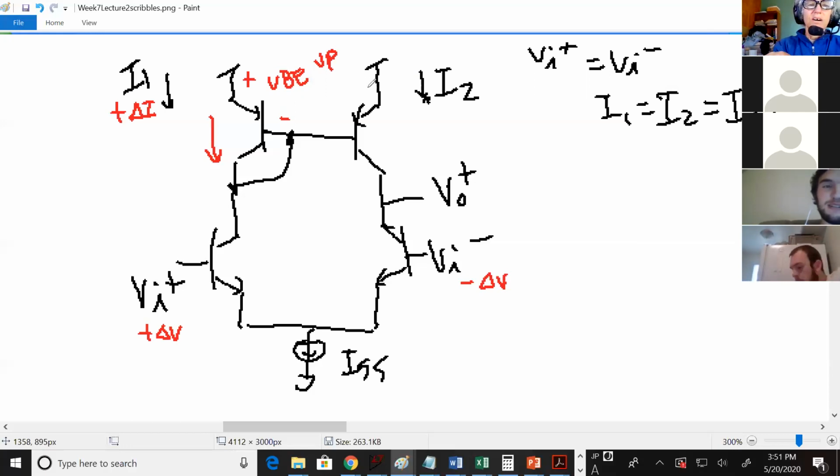So that's good. Something interesting is happening on the right side, because the right side just uses this voltage. It has no say in what that voltage is. This side said, hey, I'm getting more current, so I'm going to increase my VBE. What happens to this node when VBE increases? When the VBE on the left side goes up, this goes lower. And what happens to this VBE here? It's bigger. So both of these VBEs go up. Okay, so that's step 1. The VBE of this is going up.